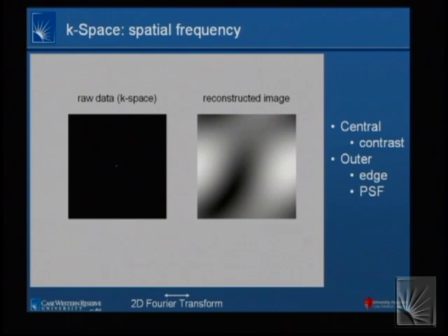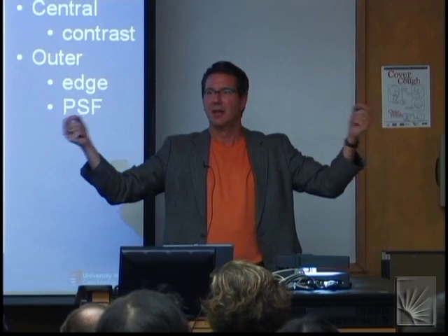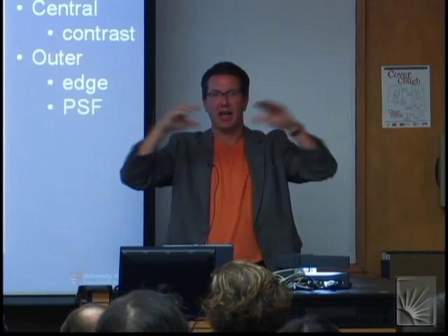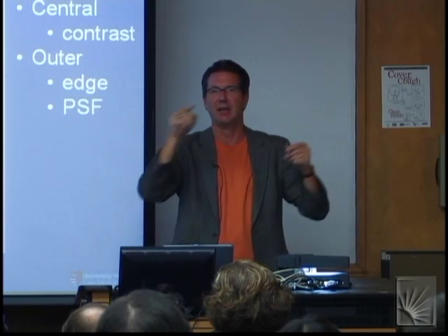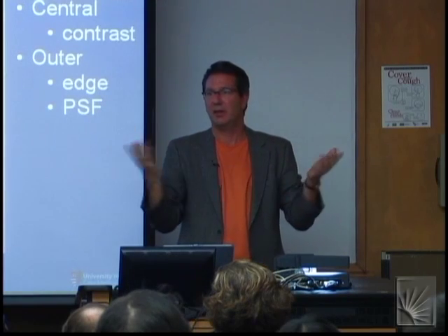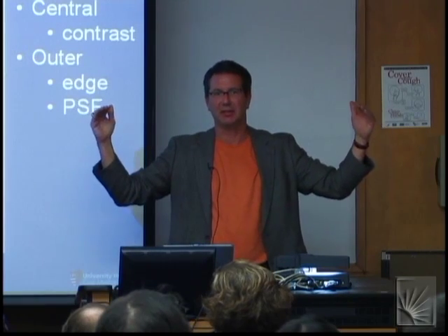So think one-dimensionally, and think of a spectrum, okay? We have minus Fs over 2 to plus Fs over 2. What's right at the center? DC, right? And so how much variation, how much information do I have about the variability of a signal at DC? None, right? That's just the average level, okay?